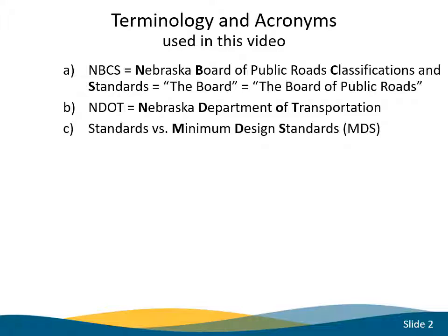MDS refers to the minimum design standards, which address only the design aspect of a work or project. Standards are often termed minimum, but realize there are maximums for superelevation and grade, and ranges for cross slopes. When we say minimum, sometimes it refers to all of those.